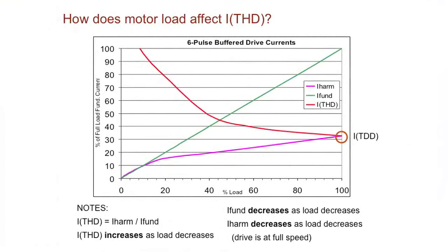If we look at this, this is your THD here. I was looking at voltage. Here's your I fundamental, your fundamental current coming up. Here's your current distortion, your current THD, and then here is your I harm, or your TDD.